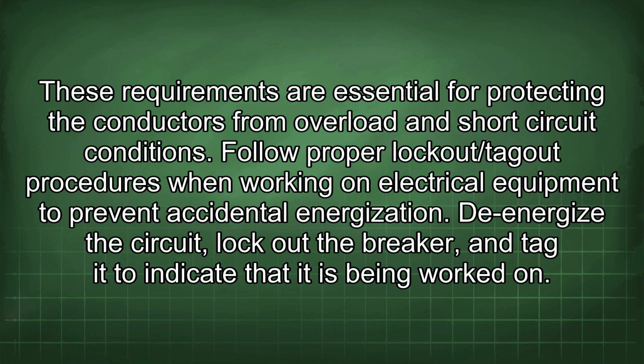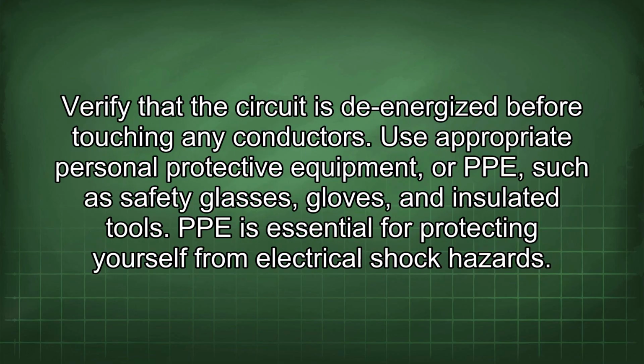Follow proper lockout/tagout procedures when working on electrical equipment to prevent accidental energization. To de-energize the circuit, lock out the breaker and tag it to indicate that it is being worked on. Verify that the circuit is de-energized before touching any conductors.